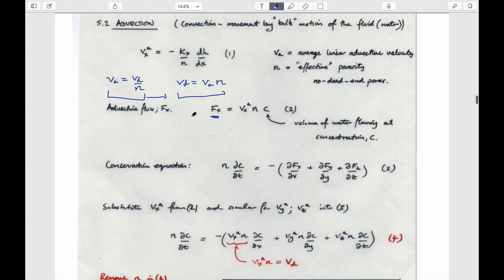So you can think of the mass that's traveled by the solute dissolved in water. Before it was by diffusion, Fick's law, remember? We said that the diffusive flux was equal to the diffusion coefficient times the concentration gradient. If we look at the flux that's carried downstream, the amount of solute dissolved in water that's carried downstream, it's carried by the Darcy velocity.